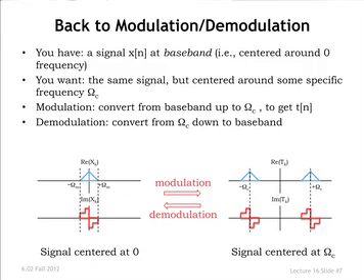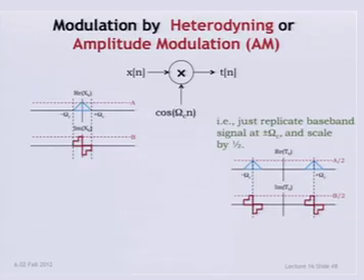So just to look at that in a little more detail, this is the modulation process we talked about last time. You've got a time domain signal, your information signal. You multiply it by the cosine to get an amplitude modulated transmitted signal. So t of n is the signal that you transmit. Okay. There are other names for this. This process of multiplying a signal by a cosine at a particular frequency is referred to as heterodyning. That's a term from the earliest days of amplitude modulation, I think invented by Fessenden, who also invented AM. And of course, it's specifically amplitude modulation for us.